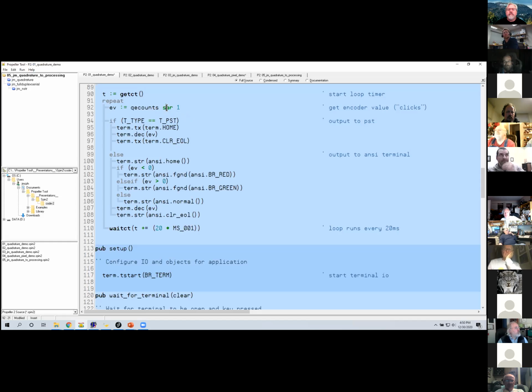SAR is a way of dividing a number and maintaining its sign in case it was negative. And the reason I'm doing this is part of it is habit. When you do multiplication and division with a microcontroller, they're expensive in terms of code. Now in the P1, they were really expensive. In the P2, much, much less so because we have the CORDIC solver for multiplying and dividing. So multiplying and dividing in the P2 is much, much faster.